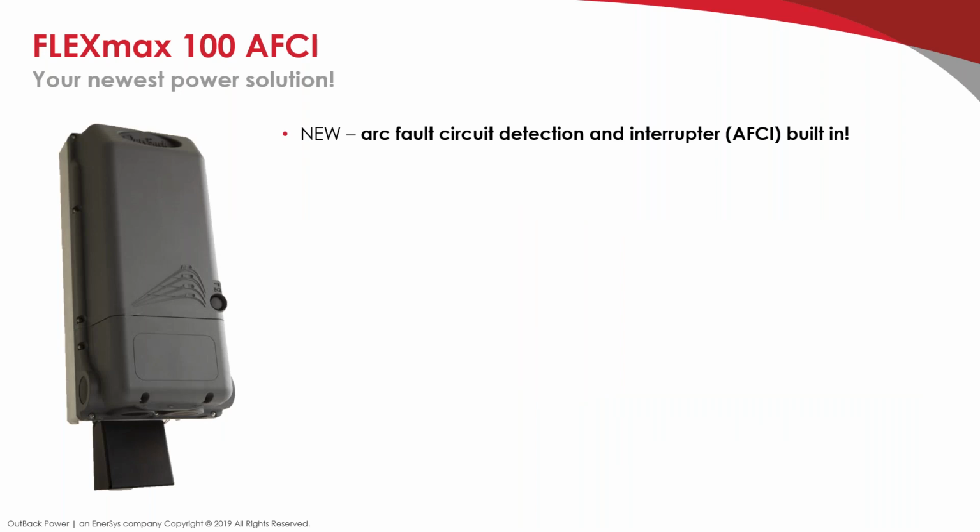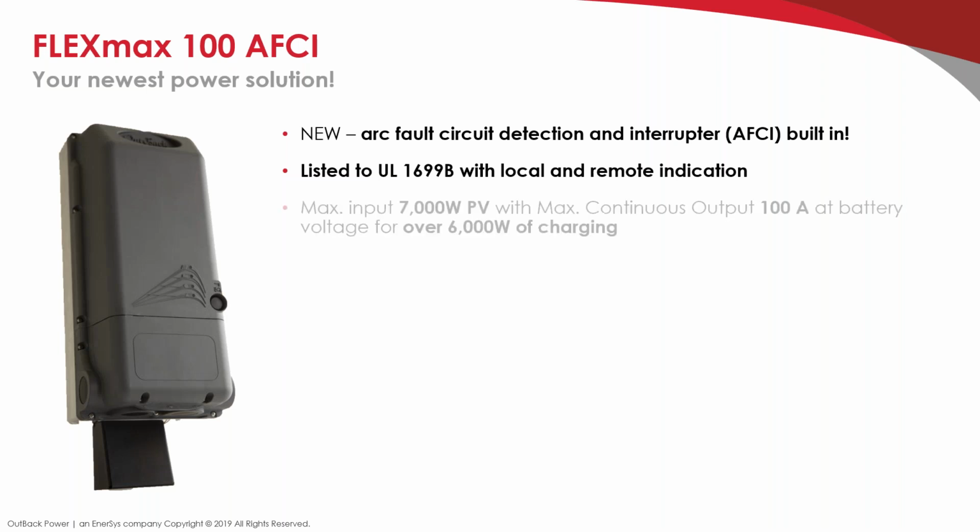So really, the goal there is to maximize return on investment. So once again, the arc fault detection and interruption is built in, and we'll see what that looks like here in a bit. It's listed to UL 1699B with local and remote indication. So that's a UL requirement for AFCI that feeds into the NEC. We are tested and listed to that requirement.